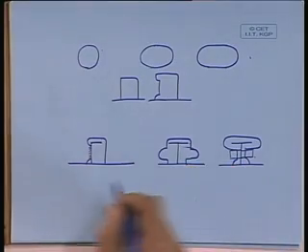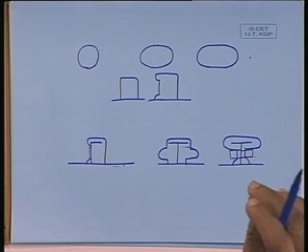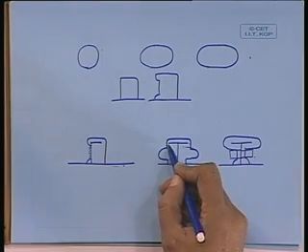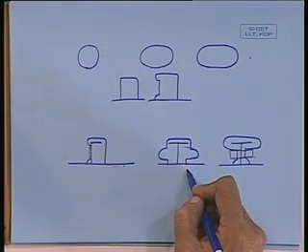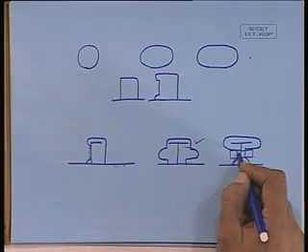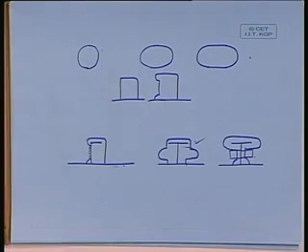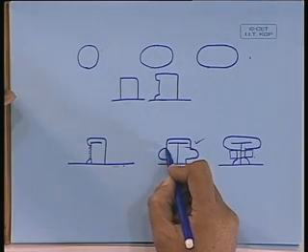You see what happens, you take the bottom, you weld this, and then you will take the floor and try to put it on top of it. So this part should be all clear, and therefore this goes well. Whereas this part will create a problem. You have to take one by one and then put it in position and then try to weld it. That becomes a difficult part. You cannot put it directly, you have to slide it along the length. So that is why they have gone for this.